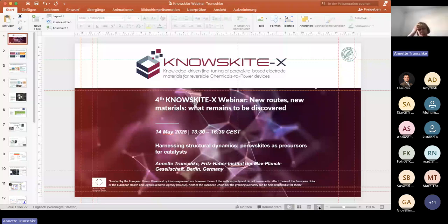And we analyzed the structure of all the materials in this series very carefully by Rietveld refinement, also by XRD, classical techniques, and we found that the substitution of manganese by copper gives a very complex correlation. We never found any linear correlation of the lattice parameter, for example, with the copper content, and other structural parameters were also not following linear correlations.